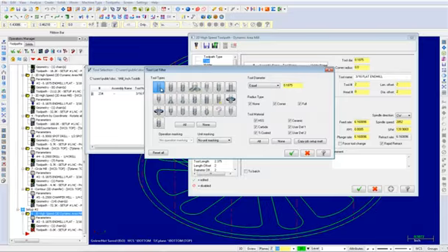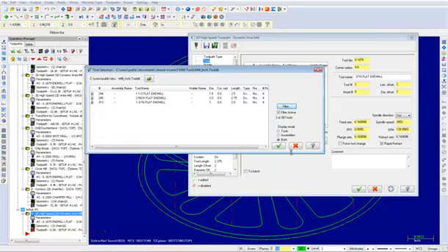Also, under Tool Diameter, pick Greater Than and input a value of 1. Once complete, select the OK button to exit the Tool List filter. In the Tool Selection dialog box, you should now only see flat end mills larger than 1 inch. That being said, choose the 1.5 inch flat end mill and then select the OK button.